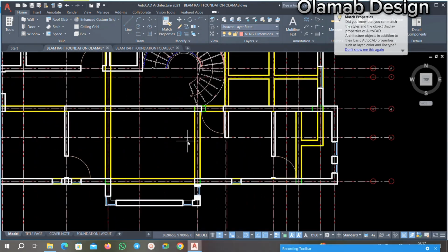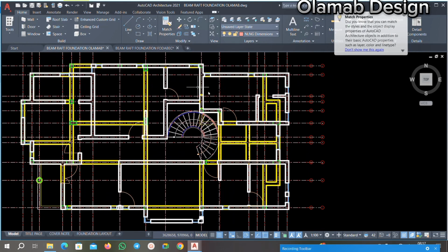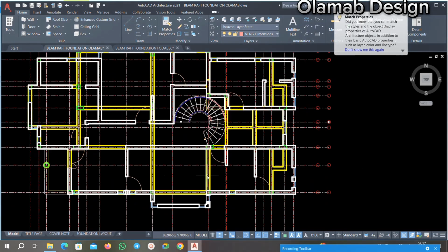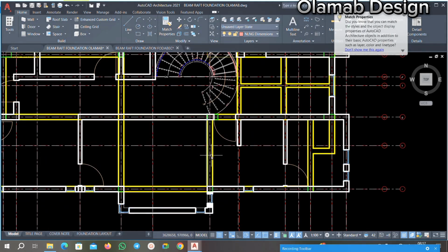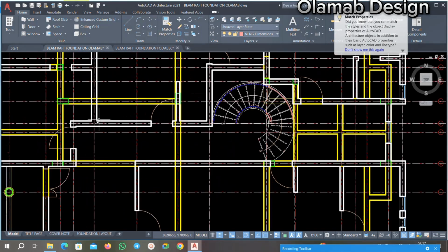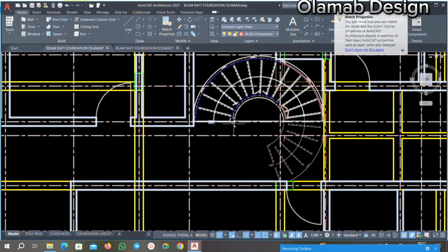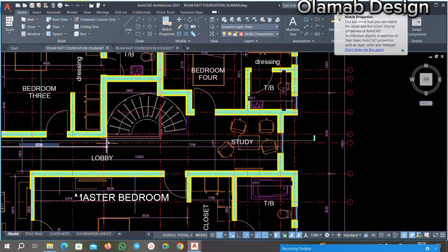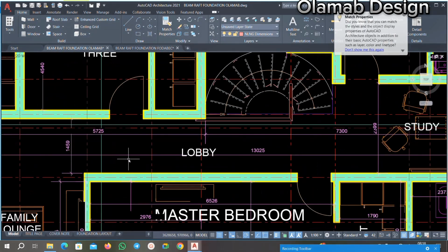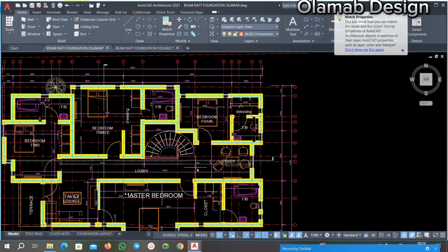So what we are going to do now is, actually we've even done a perfect general arrangement here. As you can see, we've divided this span at this point. But these particular beams, we need to run them straight down, because there is a lobby at this point. If you go to your first floor, you see that you have a lobby there. Can you see? So we need a beam here to also assist this staircase.